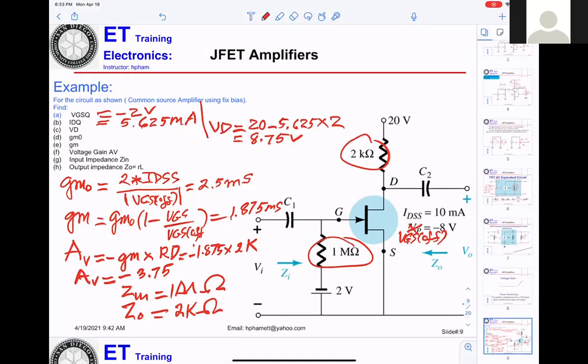So I'd calculate the output impedance based on the drain resistance and the internal drain resistance of the FET, and then calculate the power transfer to the load based on that output impedance. I was just doing it the way the model Mr. Pham has given in the past. That's just normal.